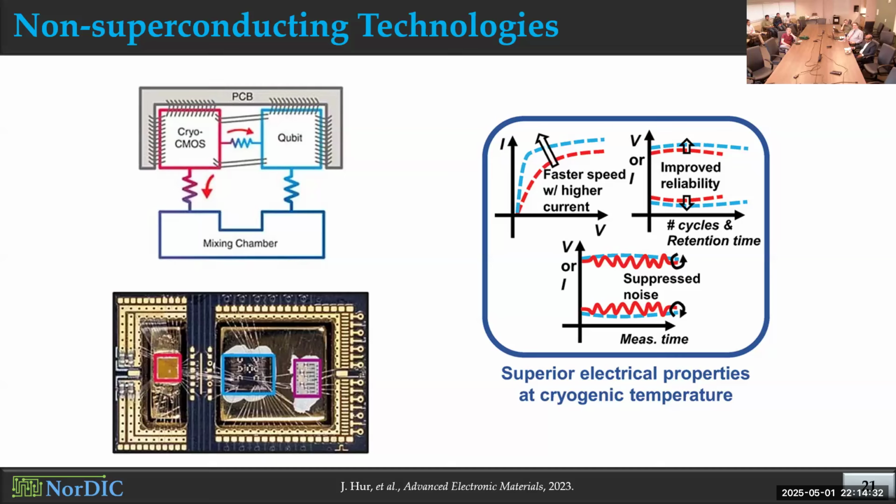That's not true. Threshold voltage increases for MOSFETs at cold. Yeah, actually, voltage overhead is a real problem at cryogenic CMOS. That's true, but we also have sharper turn on, right? The sub-threshold slope is steeper, and we can use lower VDD because we can reach the on current. Yes, threshold voltage increases, but because of the sharper turn on, we can actually use lower VDD and we can reach the on current much faster. So from that, we get better power efficiency and energy efficiency.